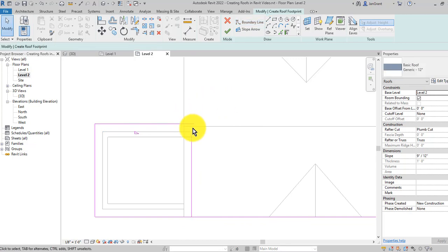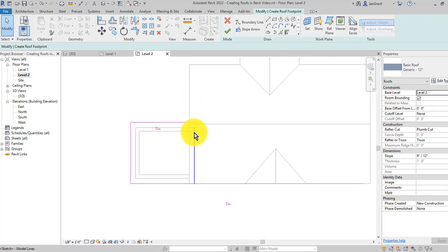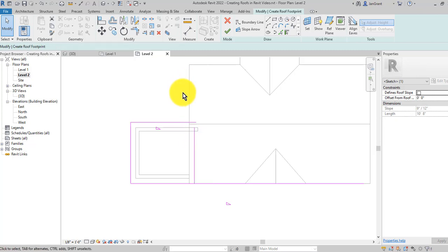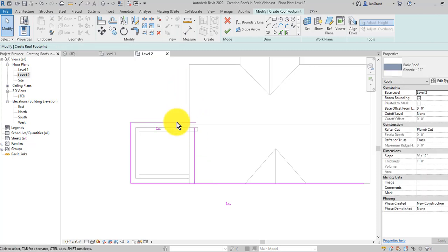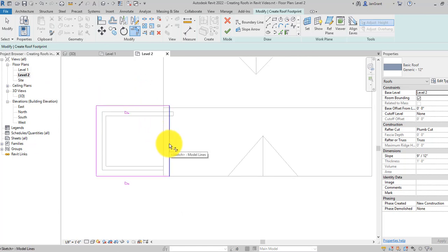See what I did? I am sketching this so that I can have this line up with that wall, but I need to close it, right? And I have this extended piece here. So I'm going to use this trim extend corner to click on these 2 lines and click on these 2 lines. And now I have this box. That's what I wanted to end up with, guys. I want to end up with a box. I can always stretch this out if I need to. And that's what I usually do anyway. Stretch it out to catch that wall.